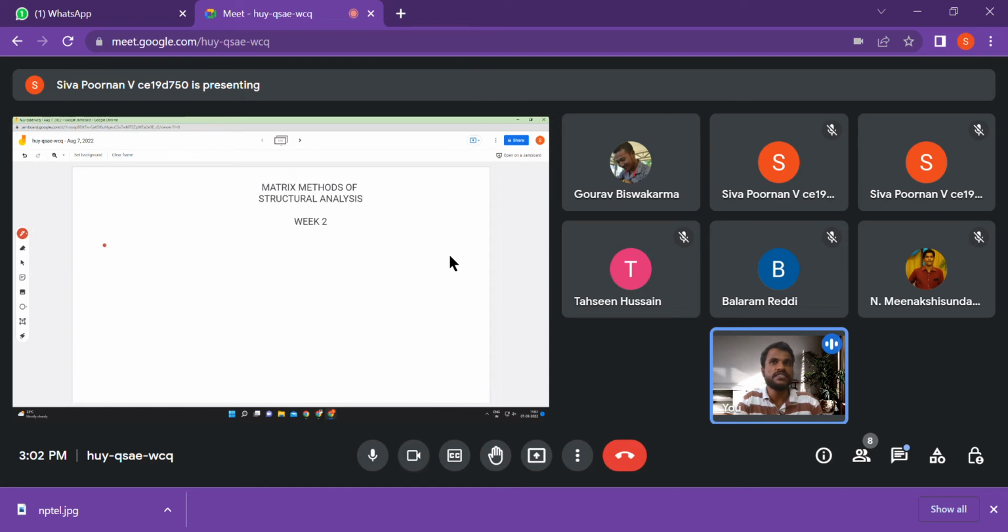We were discussing, so I hope my screen is visible, right? Yes. Okay. So what was the question? There was a beam, and both the angles were known. So let's say we have a simply supported beam. Both the angles at the ends are known, so let's say theta 1 and theta 2 are both known to us. Is it enough to ascertain the complete profile or the elastic curve of the beam?